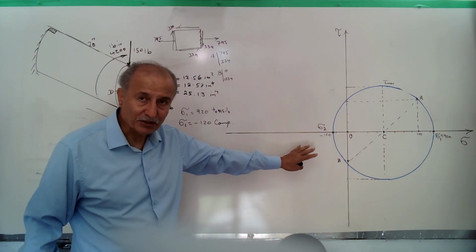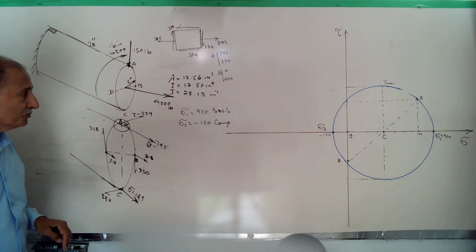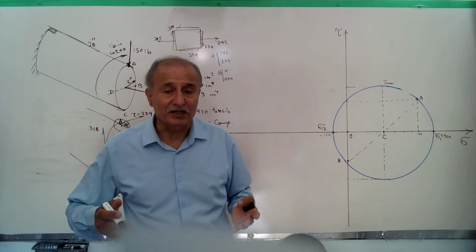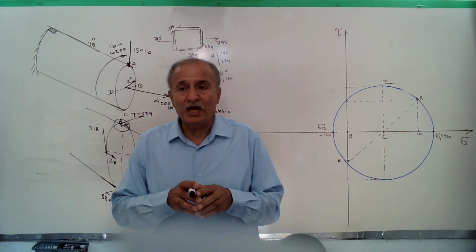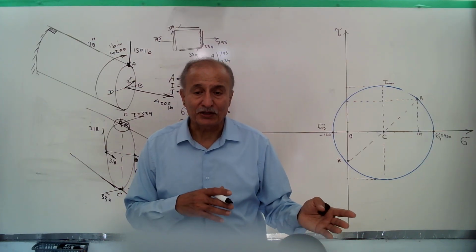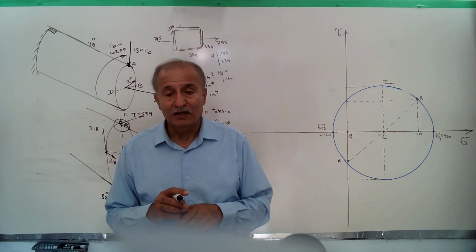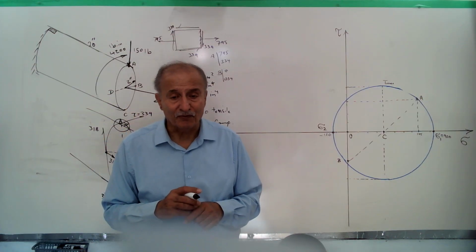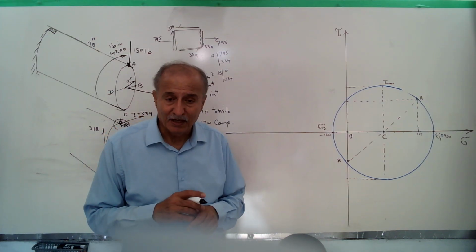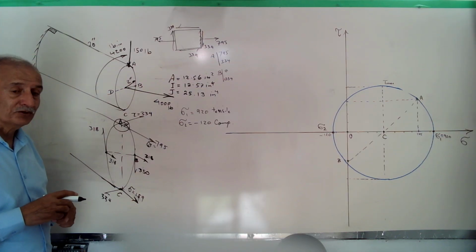Actually, here is a two-dimensional Mohr circle to find out the maximum stress that can happen inside the material. The real Mohr circle is 3D, but in engineering, you can reduce many 3D problems into 2D and calculate the stresses. This answer is satisfactory for three-dimensional as well. Many problems can be converted from 3D to 2D to make the calculation easier, faster, and shorter in time. But not all problems can be converted to a 2D problem.